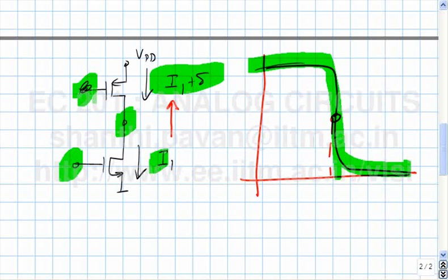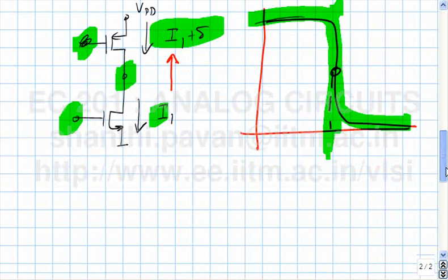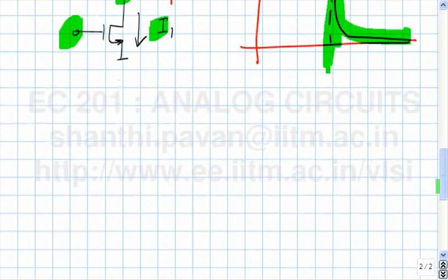We've used it in a negative feedback loop to make the input-output characteristics of the feedback system independent of the properties of the forward amplifier. So, all these high gain amplifiers should never be operated open loop, okay? They will always be operated in the feedback loop, which will force the amplifier to be operating in this region. So, please remember this as a general rule. A high gain amplifier can never be operated open loop, because even a small change in the operating point will cause the output to saturate.